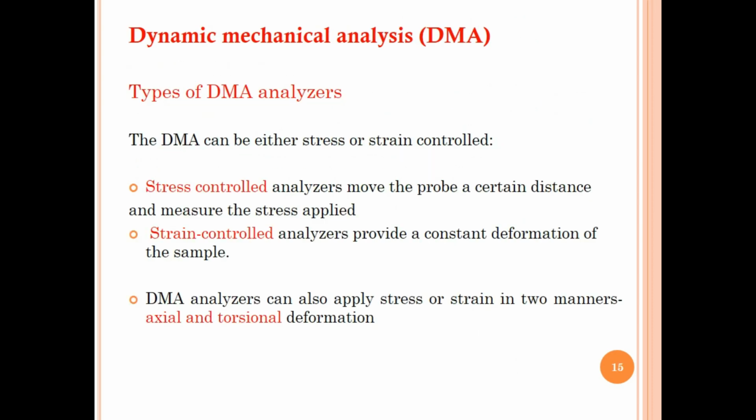Now we discuss the types of DMA analyzers. The DMA can be either stress or strain controlled. In stress controlled analyzers, we move the probe a certain distance and measure the stress applied, while a strain controlled analyzer provides a constant deformation of the sample.